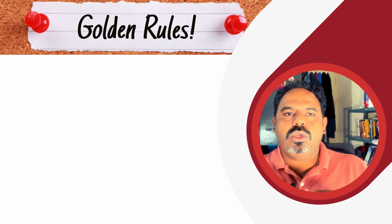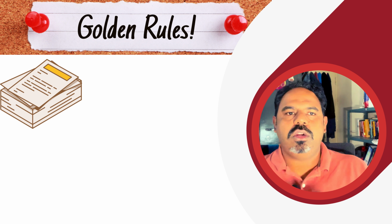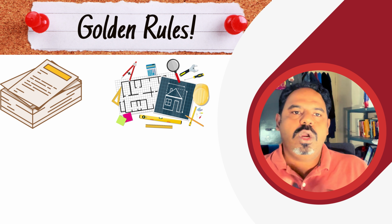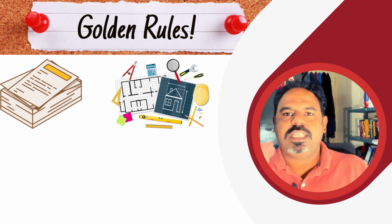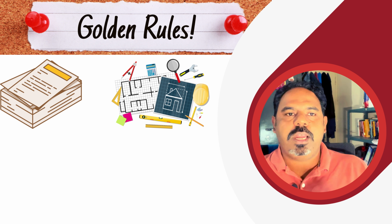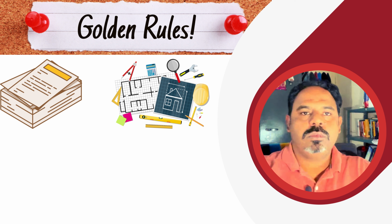The HIRA team should always get all the necessary reports and documents before start of the HIRA process, such as construction drawings, work method statement, past accident records and their analysis, original equipment manufacturer manuals, safety data sheets, lifting plans, and any other necessary documentation.